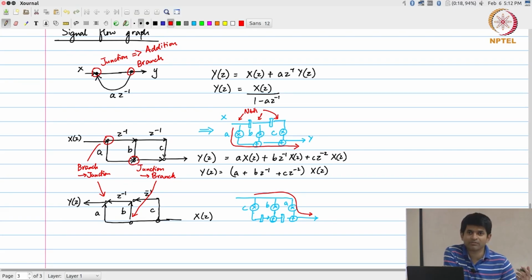If I take two n bit numbers and multiply them, strictly speaking, I need 2n bits in order to represent the result. So in this case, the multiplication is happening right here. This is n bits, but this is greater than n bits after the multiplier. So the shifters now need to be bigger or wider.